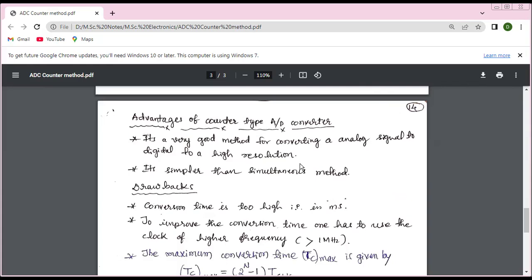Suppose your threshold input voltage is 0.5 volt, and you have applied 0.1 volt. 0.1 volt is less than the minimum voltage, so that will not be sensed. That means you can't use this circuit for lower voltages like 0.1, 0.2. So this is what resolution is. So it has a good resolution. According to design, you can even apply millivolts to get the output.